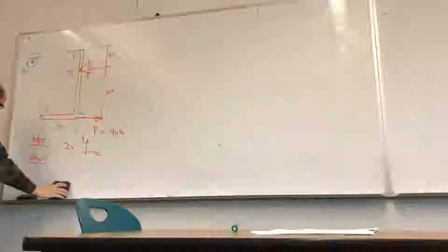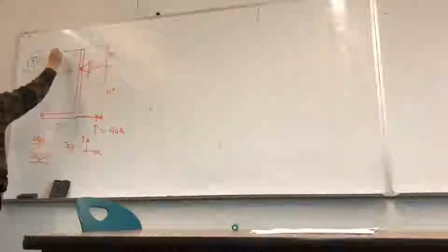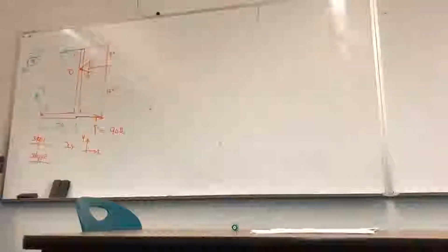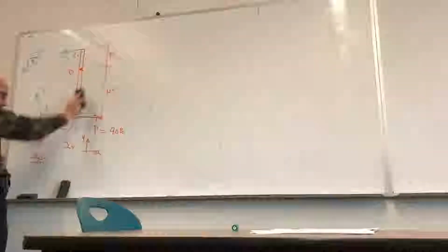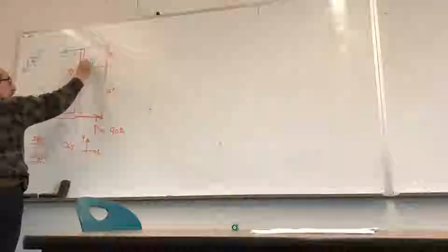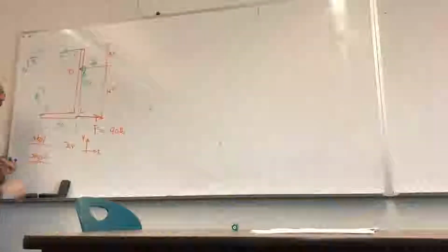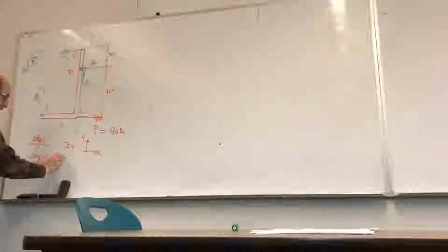In other words, the same force acts in that cable here and here. How about here? If I remove this, that represents two unknowns. Let's assume these two unknowns are this way and this way. So that is the free body diagram.